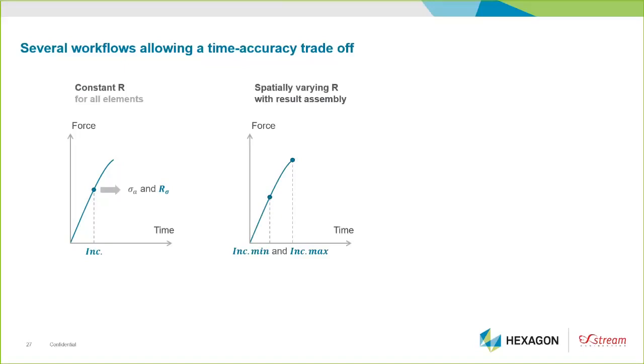Those two extrema lead to two stress fields, considered as the maximum and minimum stress field per element, leading to a different stress amplitude and load ratio per element. So each element has its own stress amplitude and load ratio. And this can vary with the load amplitude depending on geometric nonlinearity, boundary condition effects, etc. So that's really a good fit to capture the fact that locally the load ratio will be different per element.